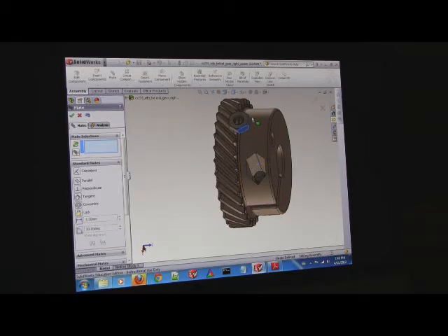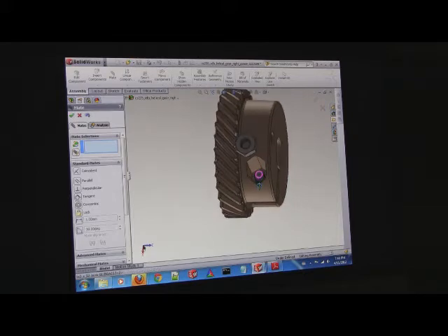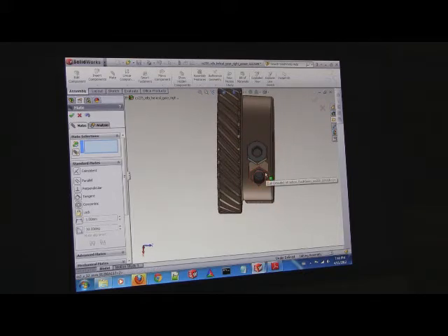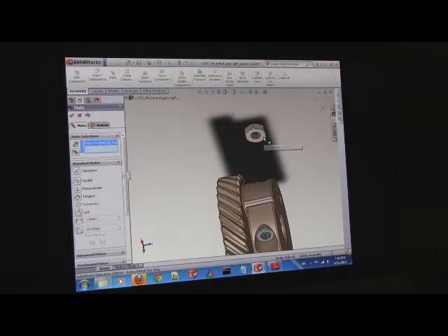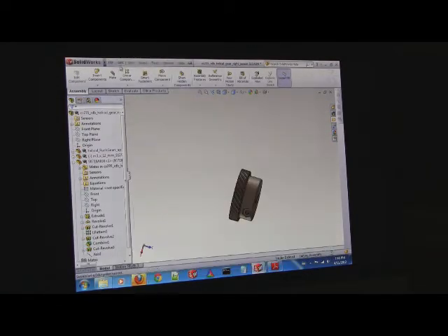And again, drag your nut around and see that we've further constrained it. It can no longer spin about that axis. Now the last step, select the bottom of the hex hole and then select the bottom of the nut. It moves right into place, hit the green check mark, and that assembly is done. And just save it. It's not like in reality where you're clamping it and pressing it, but in SolidWorks there are no slip fits or press fits or interference fits. There's only sizes and geometry.